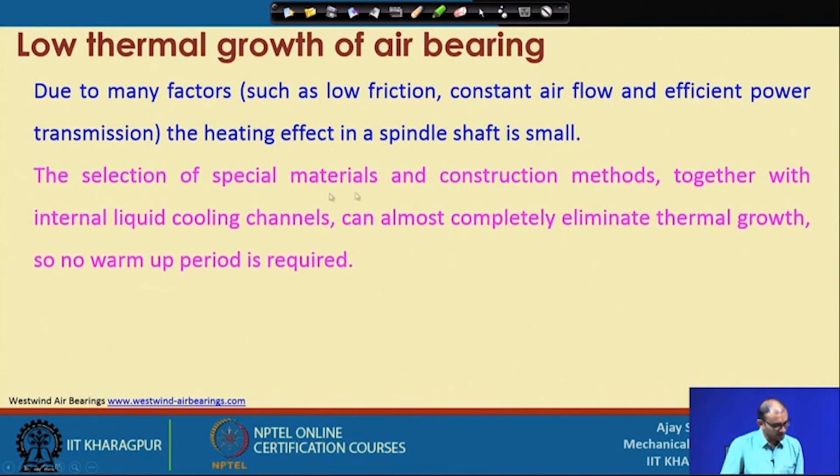There is also a selection of special materials and construction methods, together with internal liquid cooling channels. So, even if you think a small amount of thermal change will create some problem, you can provide liquid cooling channels, then you can completely eliminate thermal growth, and no warm up period is required. So, what is this warm up period?